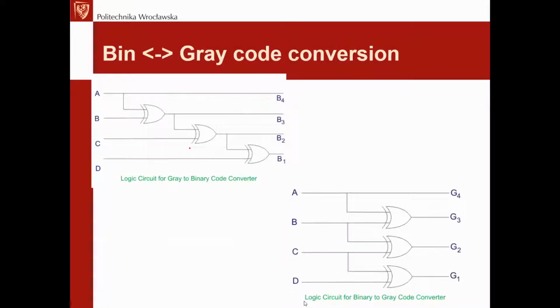We'll talk about the logic, and what the gate means, in the short term, because it's the plan for today, or maybe early next week. But in general, the decoding between the gray code and binary is very simple. It requires just 3 XOR gates, and that's it.